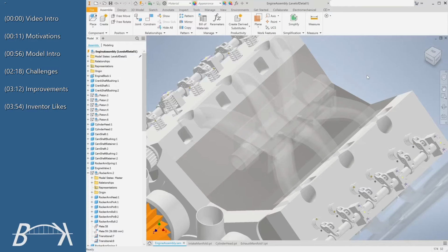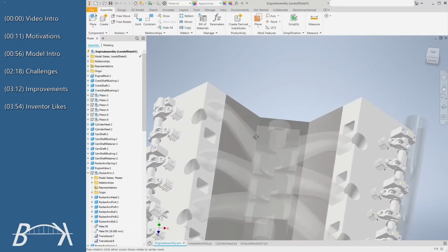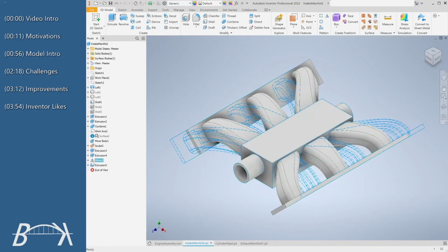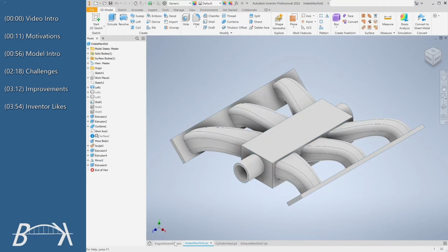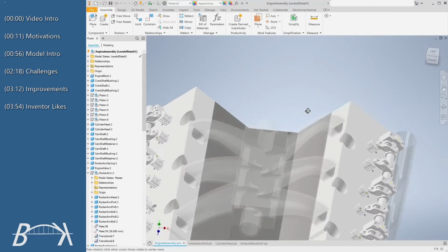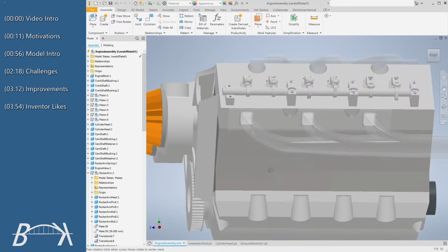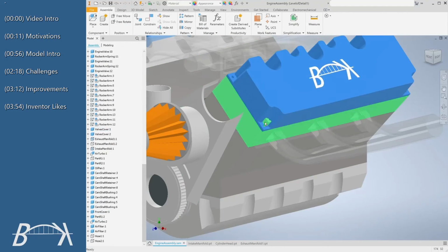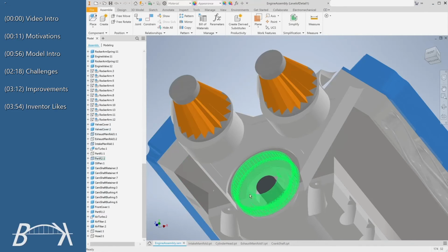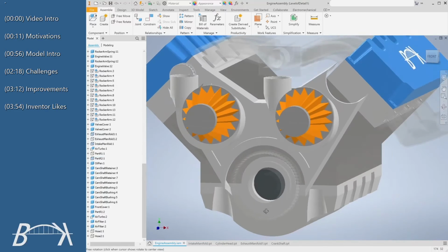I was appreciative for having a YouTube demonstration to give me some of the specific dimensions for this engine. It had a few bad instructions I had to troubleshoot though. The intake manifold had to be mirrored to get it to line up with the offset of the cylinder heads. The exhaust didn't line up with the cylinder heads. The camshaft retainer didn't facilitate the valve cover. The diameter of the crankshaft didn't match the bushing or the pulley for the belt.